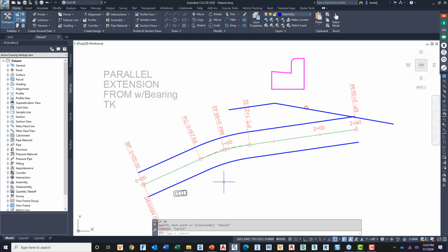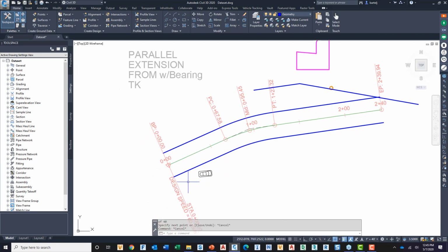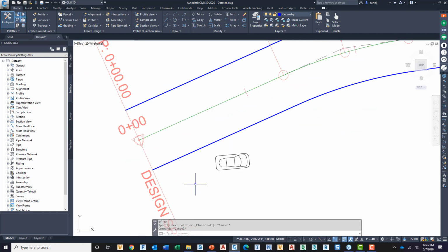In addition to that, let's factor that into another command. I've got a vehicle here on the screen that I'd like to put in the center of the lane. I don't know what the rotation is. I don't necessarily know what the width is, but I can use the object snaps we've looked at so far to derive that. What I'm going to do is rotate my object around the midpoint of the back, and then I'm going to say reference. My reference line will be the midpoint of the back, the midpoint of the front, and I'd like that to match parallel to my street. We'll acquire that, pull in that direction, and it locks into that position.